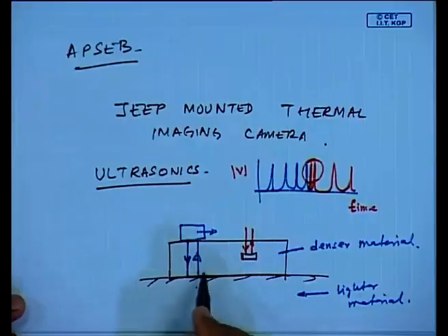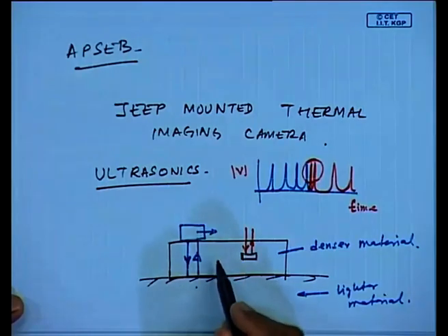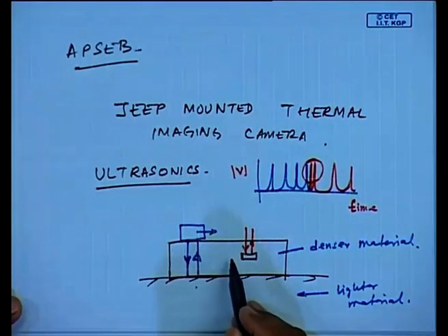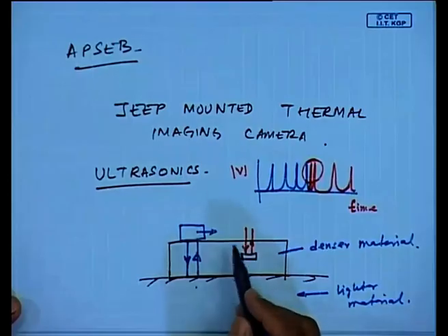In fact, the ultrasonic thickness gauge is based on this principle. If I know the speed of the ultrasonic wave in this medium, I can calculate, from the time taken, the distance or the thickness of the specimen.